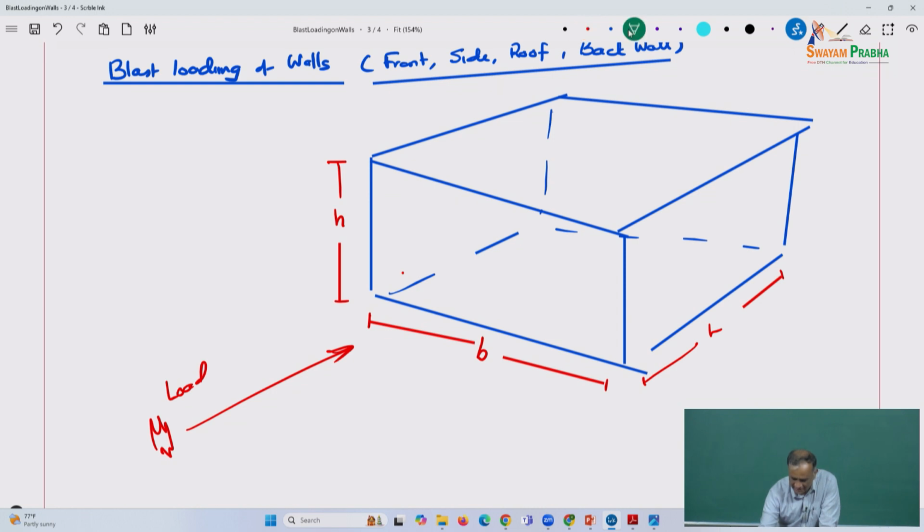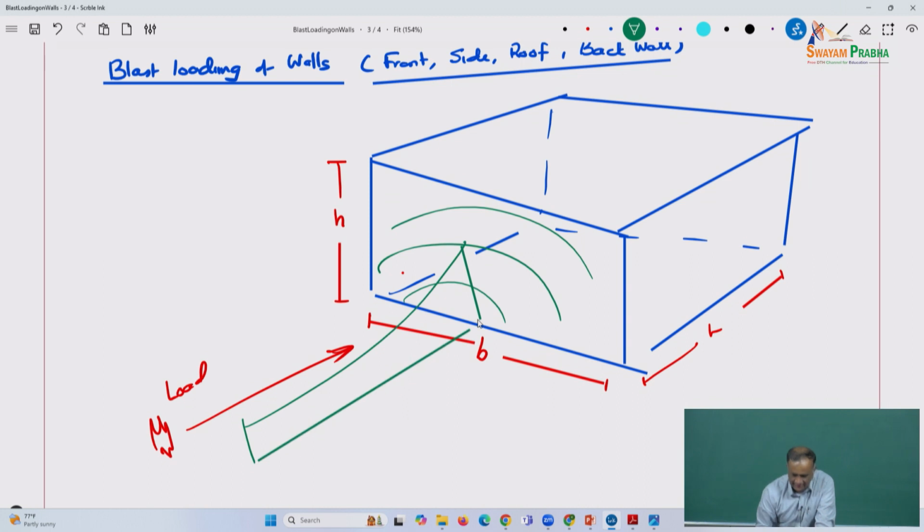And as we have seen yesterday, here is where you have the blast load itself. The blast wave propagates from here in this manner. The tail is sort of the reverse of the Friedlander equation. Once the peak comes, it starts decaying, and that's your standoff distance. This is W and this is R.